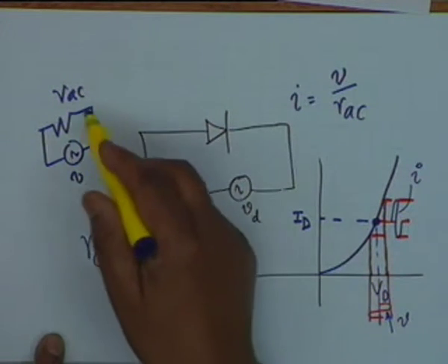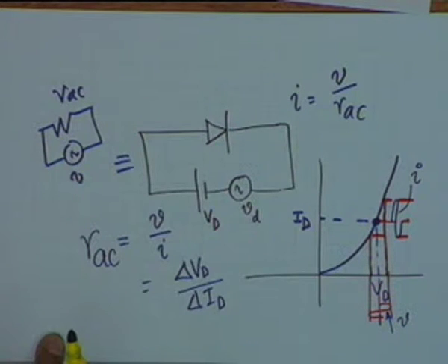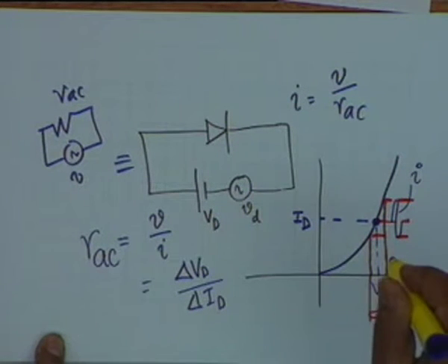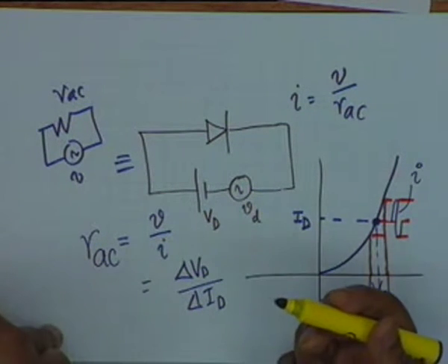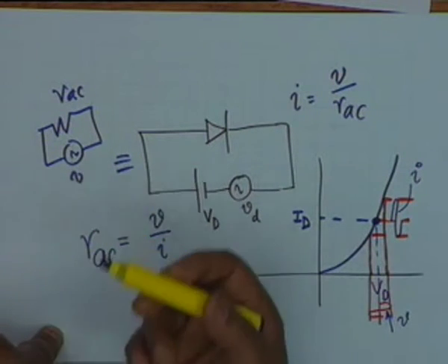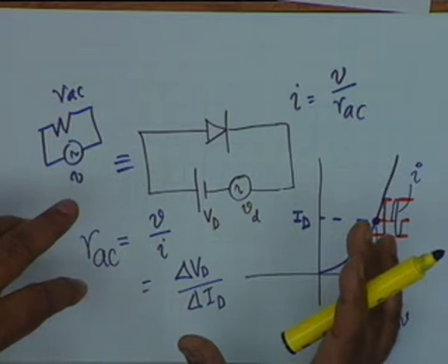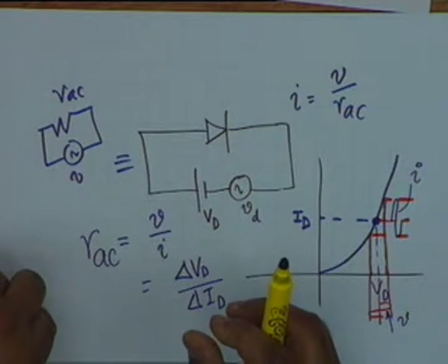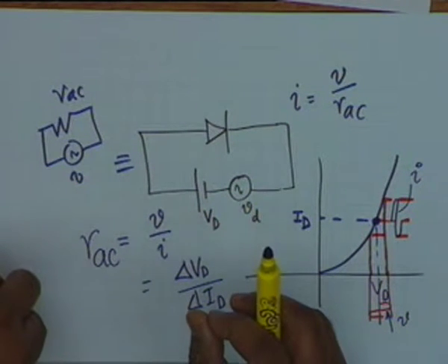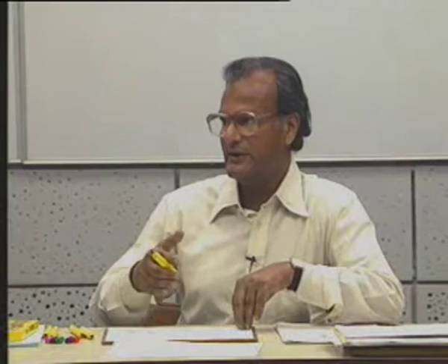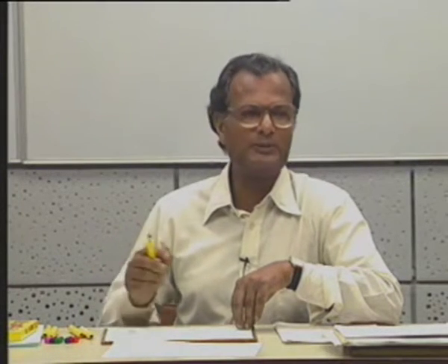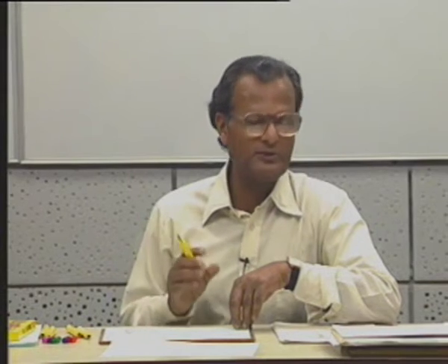This is called a small signal model of the diode. It being implied that the diode is sitting at a Q point such that it always conducts, for all values of small v. What I am doing basically is to invoke linearity. We are making a linear equivalent circuit where DC and AC can be superimposed to get the total current.